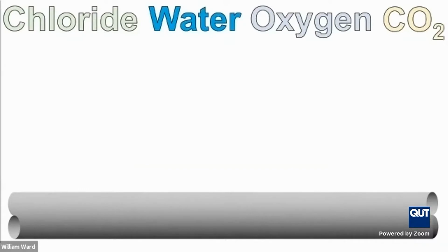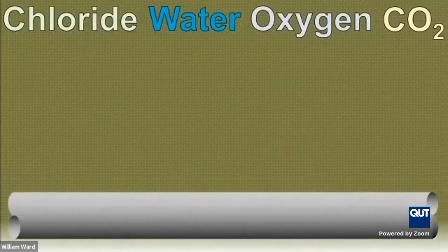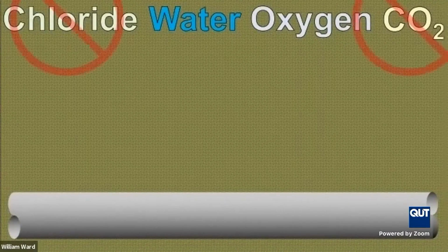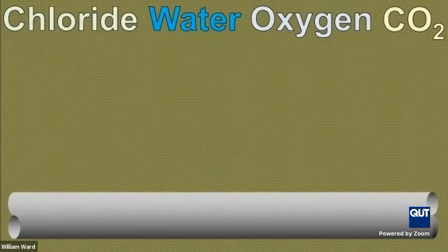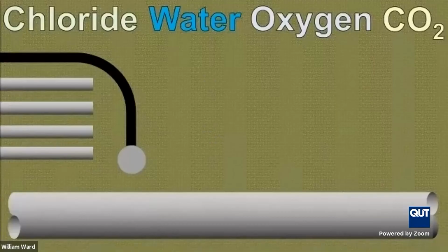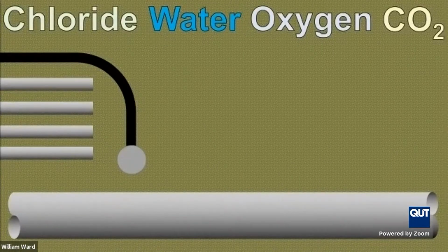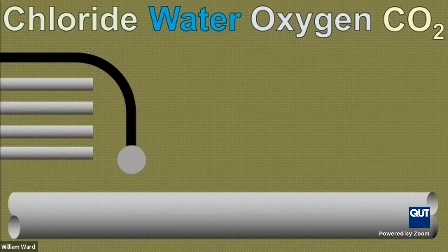And then we can continue to be a little more clever than that, because again, what we really care about is how long it takes for that concrete to become contaminated and promote corrosion. So we can't directly measure chlorides, we can't directly measure carbon dioxide, but we've already got an approach. We've evaluated, we can measure the beginning of corrosion electrochemically, so we can introduce more reinforcing steel. This is a representation of a chloride probe. So we now have a reference electrode embedded with several additional pieces of steel, which will begin to corrode because they're closer to the surface before the main reinforcing steel bar.